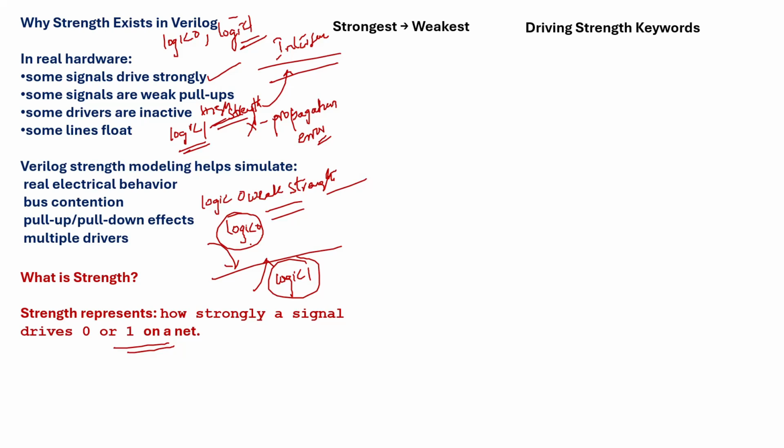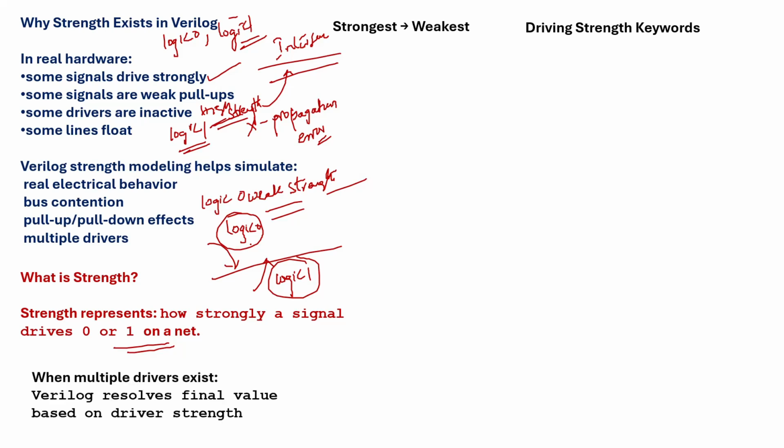If the signals from the drivers have the same strengths, who will win the race? Definitely we will get a conflict. See how we resolve this. Tri-state buffers will be used on buses to resolve these multiple driver issues. So the final value will be based on the strength we are driving, and depending upon the driving strength we get either logic 0 or logic 1.